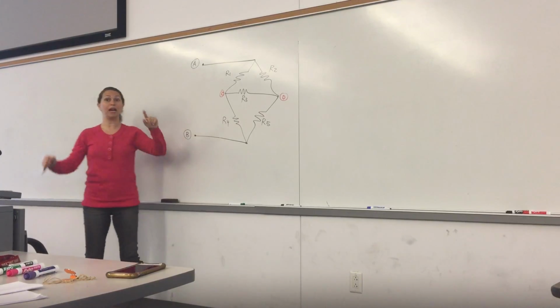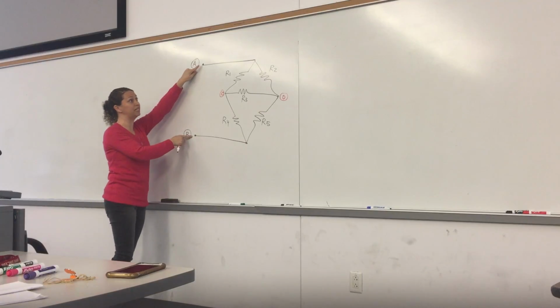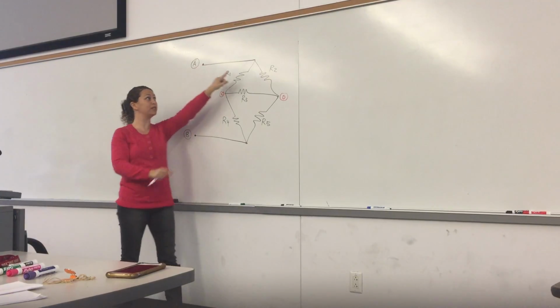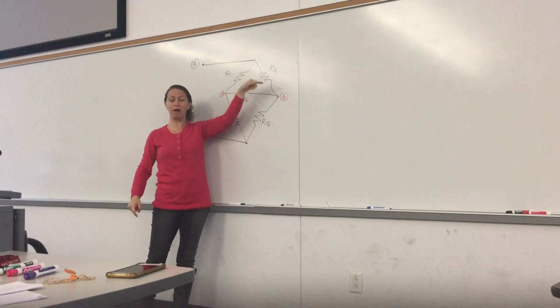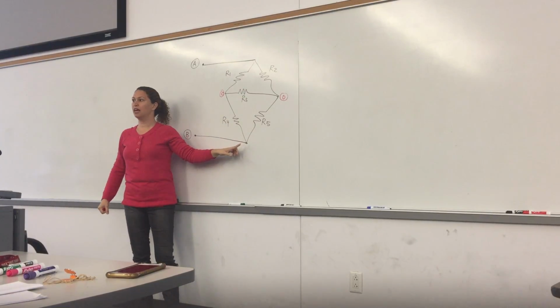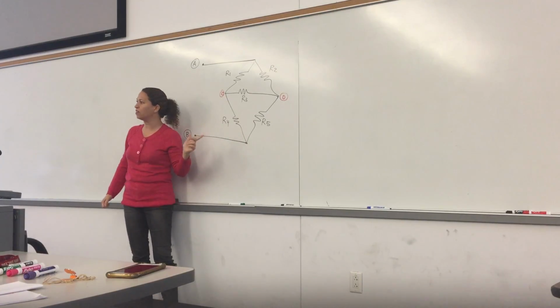I'm looking at the equivalent resistance seen between A and B, right? Can I lose A? No. I can't combine them. Can I lose B? I'm stuck. Okay? When you come to that position, you don't have any parallel resistors, you don't have any series